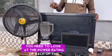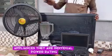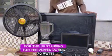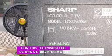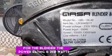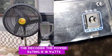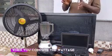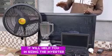So like I said, you need to look at the power rating of each of these appliances, their individual power rating. For this standing fan, the power rating is 72 watts. For this television, the power rating is 133 watts. For the blender, the power rating is 350 watts. The decoder, the power rating is 18 watts. So when you compute the wattage, it will help you in sizing the inverter.